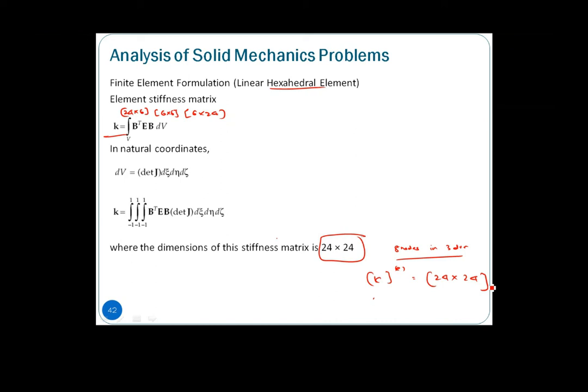Again, basically it follows the same. It can be formulated using the same isoparametric methods. So we have demonstrated, from 2-dimensional using linear triangular elements to quadratic triangle elements, or so-called LST, then to linear quadrilateral elements, now towards 3-dimensional linear hexahedral elements, where all can be formulated using isoparametric methods.